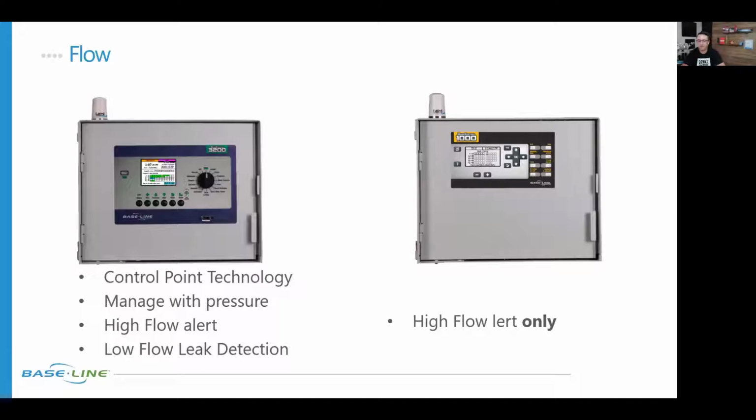Yeah, so if you think about low flow, obviously you could have clogged heads. You could have pipes that have been impaired. You could have valves that aren't completely opening. Those would all be low flow alarms, or somebody that actually shut the flow control off at the valve.